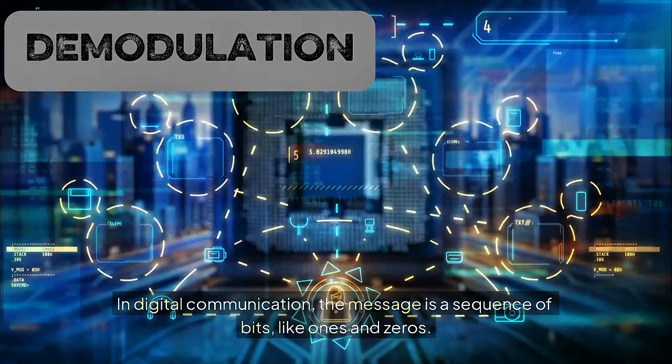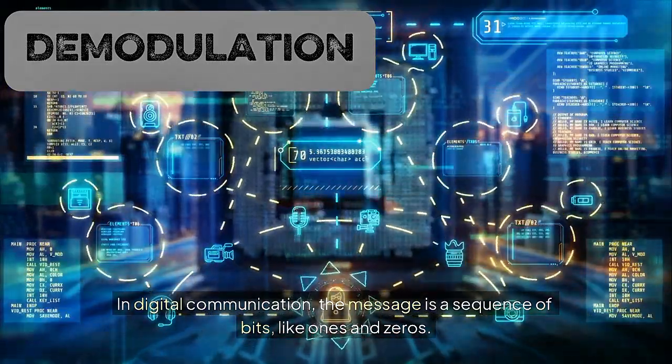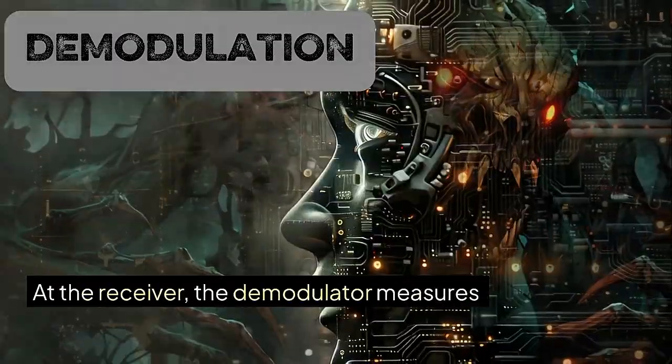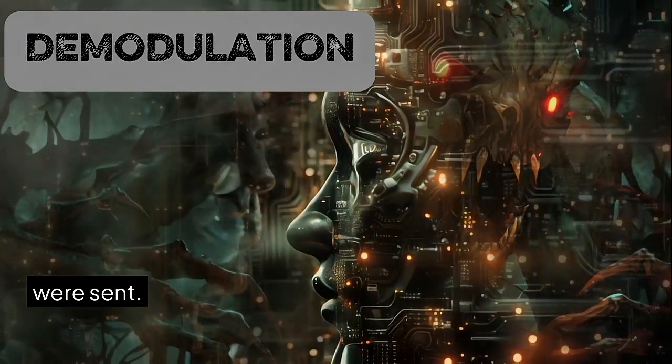Digital demodulation. In digital communication, the message is a sequence of bits, like ones and zeros. These bits are sent by changing the amplitude, frequency, or phase of the carrier. At the receiver, the demodulator measures the received signal and decides which bits were sent.